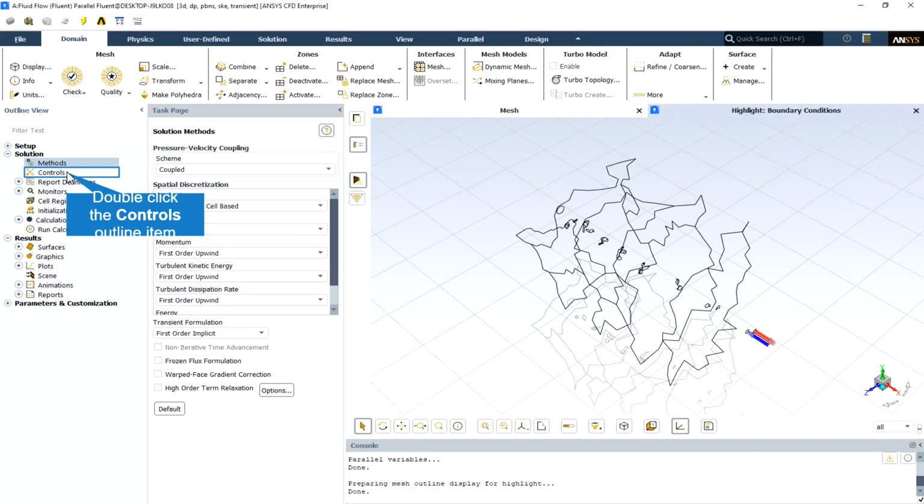As previously mentioned, the pressure-based solver allows you to solve your flow problem in either a segregated or coupled manner. Using the coupled approach offers some advantages over the non-coupled or segregated approach like SIMPLE or SIMPLEC. The coupled scheme obtains a robust and efficient single-phase implementation for steady-state flows with superior performance compared to the segregated solution schemes.